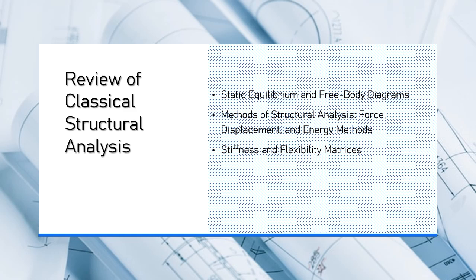In the flexibility method, forces are solved for by using the flexibility matrix. It is particularly useful in force-based analysis, such as when dealing with indeterminate structures where redundancy is present, and the solution is primarily sought in terms of forces. Both matrices are mathematically related and serve complementary purposes. The stiffness matrix focuses on calculating the structural response to applied forces in terms of displacements. The flexibility matrix focuses on calculating the response to applied forces in terms of displacements.